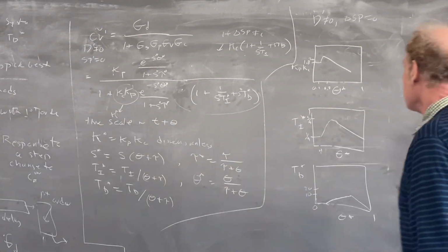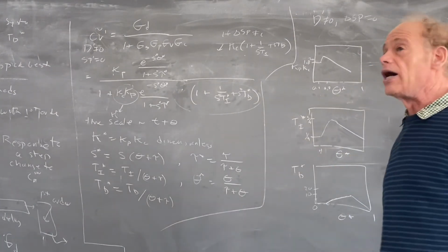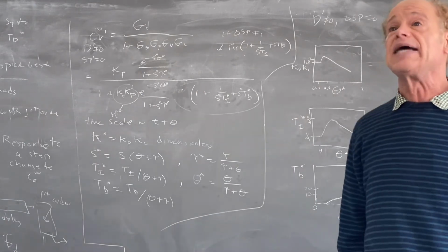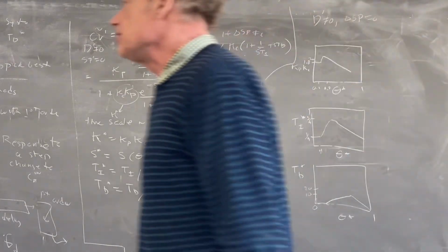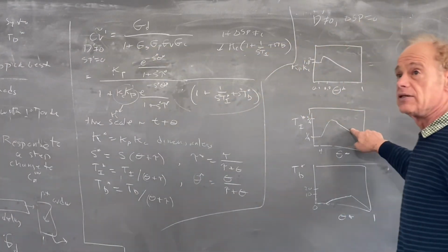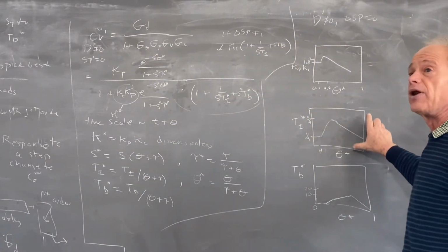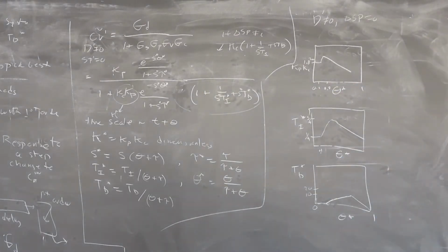And similarly, here, as the KC goes down, when theta goes up, we don't want KC going down to turn off the integral controller, because the integral controller is KC over TI, its strength. So we decrease TI along with KC, so we're still taking care of the offset. So that way the ratio is staying pretty much constant. So this guy is more or less a slave to this guy to keep the integral controller working and to make sure we don't have offset.